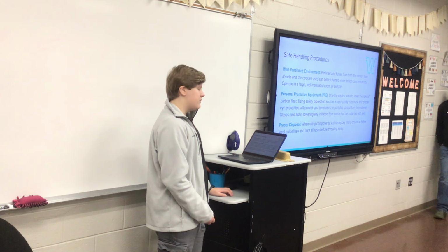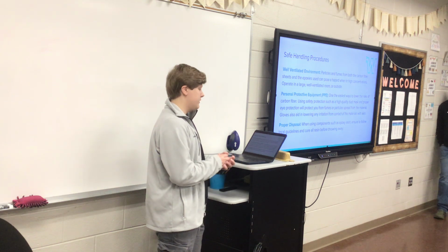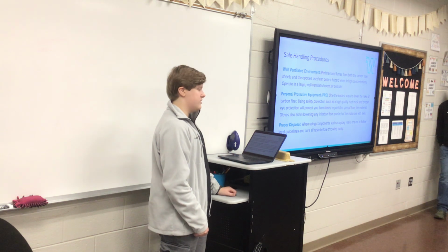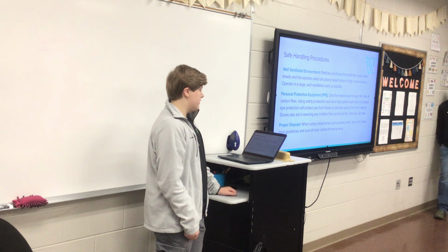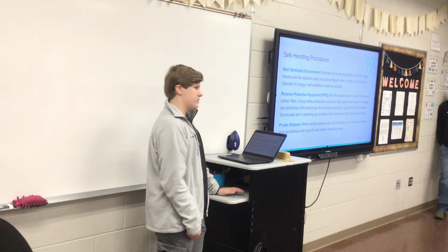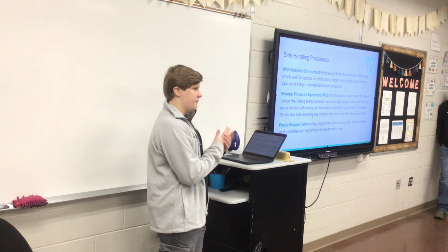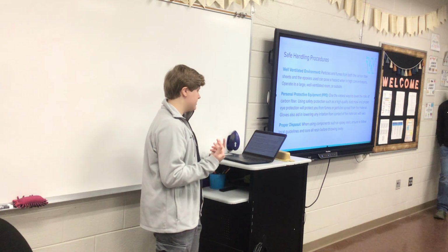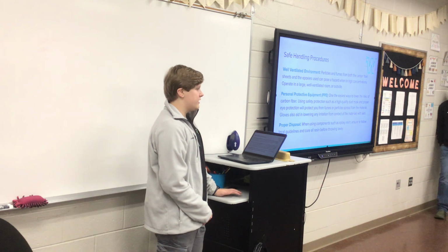And then PPE is the main way that you can protect yourself physically. You'll want to use dust masks to prevent inhaling some of those irritants, and eye protection, again, for particles. Gloves are very important because all of these tend to be contact irritants. Wearing gloves will help minimize those risks and lower any irritation or discomfort that could arise from working with these.